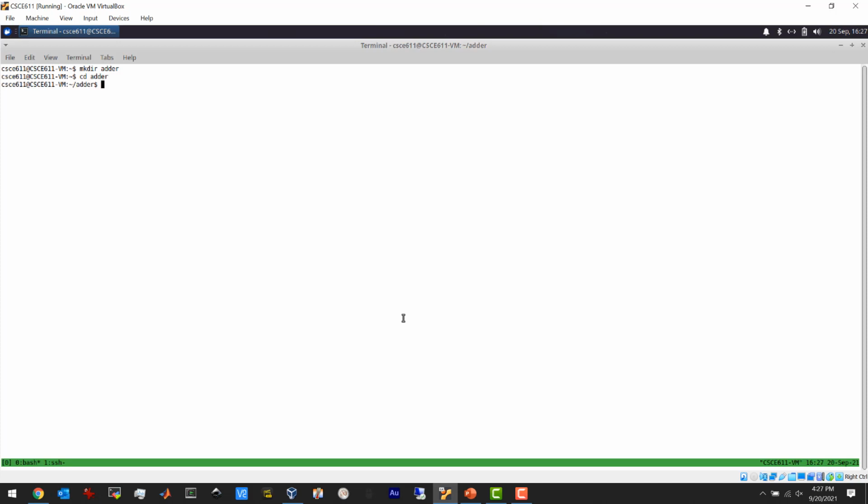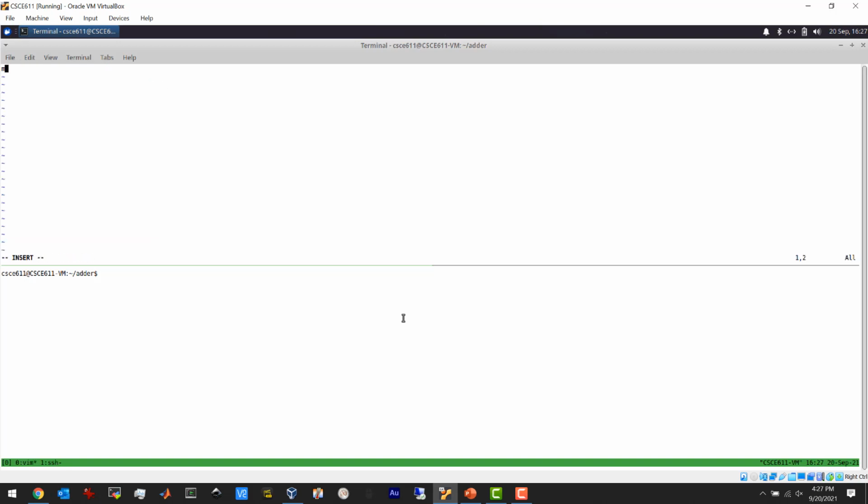I'm going to create a file called fulladder.sv. And so, module fulladder. Notice the file name is fulladder.sv, and the module name is fulladder as well, so they match. And I'll have logic input A, B, Cin, and logic output S and Cout, and I'll do endmodule. Okay, so there we go. I've got the top level design.